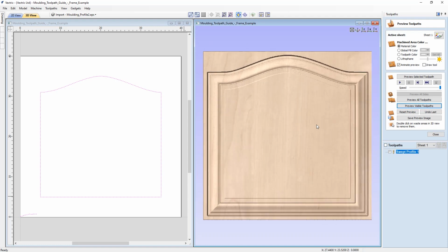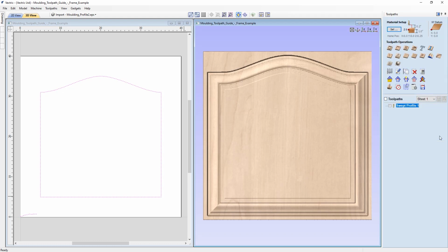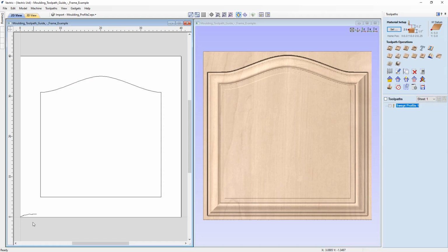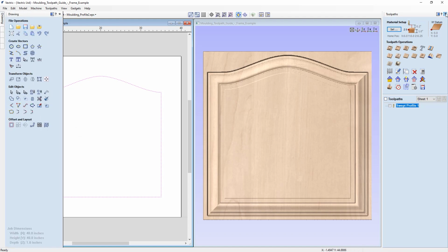Now a frame isn't really much of a frame if you've got this center point here and you've got this outside material outside of this. Let's go ahead and show you how to create the profile cuts you're going to need to cut out the center. Let's close this down. Let's off click on our 2D view and let's select our vector profile. Now you'll see down here in the bottom right hand corner, with that selected, it's 4 inches wide. We know that, and we can see that down in the bottom right-hand corner. So if we offset this vector outwards by 4 inches, then we'll have the two vectors that we need to profile this out with. Let's go back to our drawing tab again.